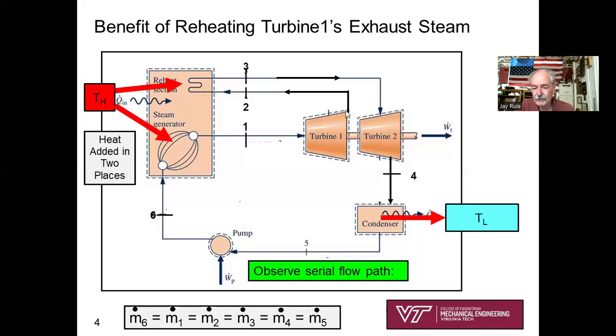Okay, reversible. So you have the ability to analyze the reversible adiabatic turbine to determine state 2, as long as you're given that pressure. And you will be given that pressure at state 2. But notice here, we're not going into turbine 2 immediately. We're coming back through piping to a reheater, back into the boiler, and we're going to be heating it back up to a given temperature and pressure.